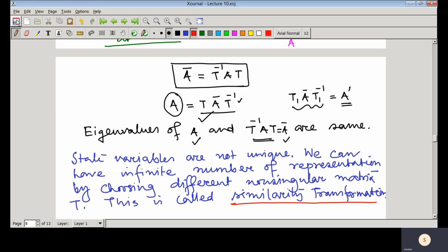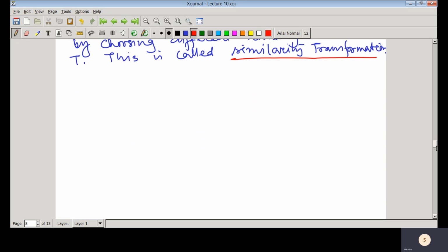So now we have solved some problems and we have discussed some important aspects of state space representation. So now we will be describing a dynamical system in state space form, and we'll be writing the general expression, that means for multi-input multi-output systems how it looks. And it is important to note that the state space representation is applicable for both linear, non-linear as well as time varying, time invariant systems.